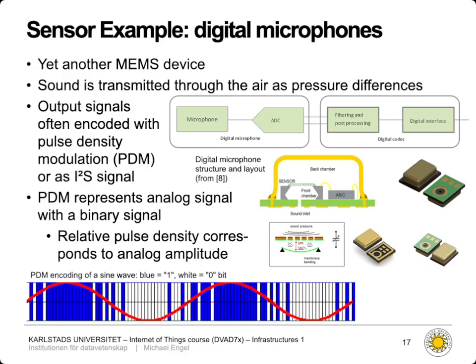And when you hit the maximum amplitude, you just get a continuous sequence of 1 bits. By reading those time after time, because you know the sampling frequency of these bits, you can figure out the frequency and, of course, the amplitude of that signal. And the higher your sampling frequency, obviously, the more precise your information about amplitude and frequency will be using pulse density modulation.